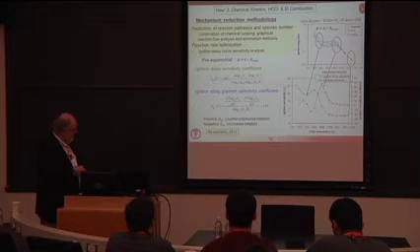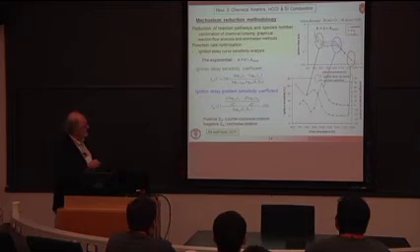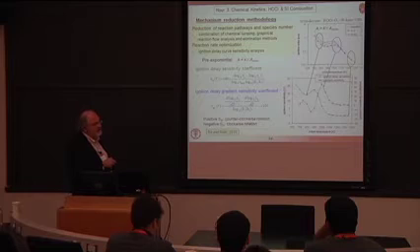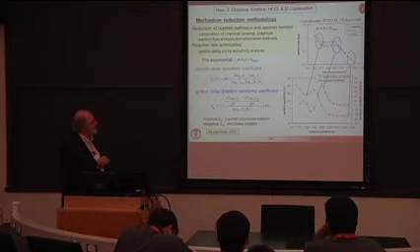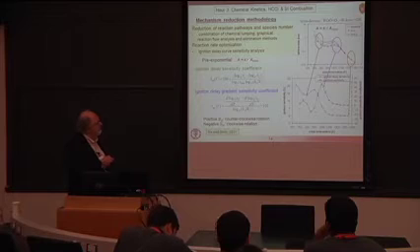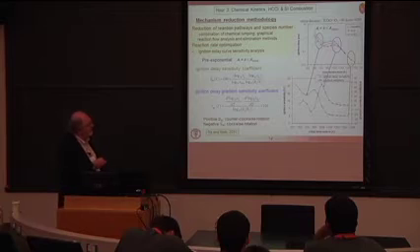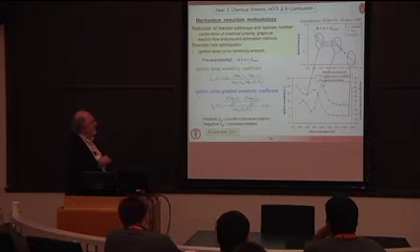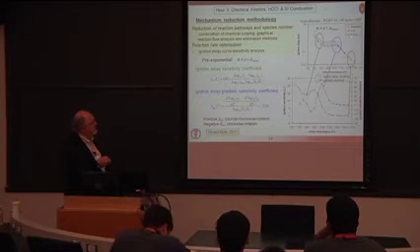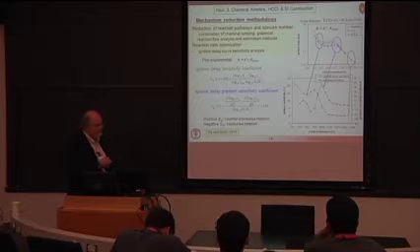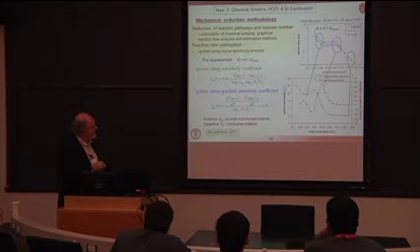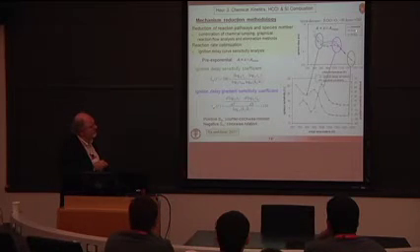One of them that Young-Chul Ra has looked at a lot is something he cooked up, which I think is actually pretty intuitive. For all of the reactions in the mechanism, you can essentially take the pre-exponential and multiply by a factor, say 2 or half, and see what happens to the ignition delay curve. So here's ignition delay versus inverse temperature, or temperature in this case, sorry. And you can see that by changing this rate coefficient, you see significant changes in the predicted ignition delay. So if you have experimental data, you can match the experimental data by appropriate choice of that constant.